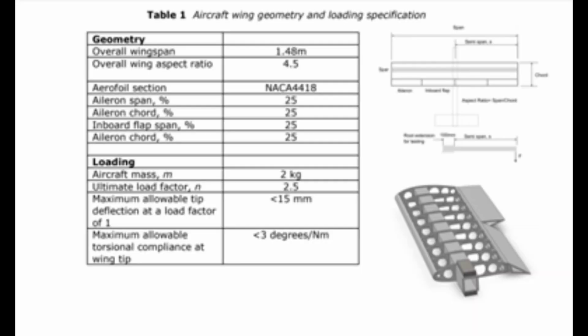The goal of this project was to design and create a wing section out of foam board, following an iterative design process. This task was set with parameters of limiting the mass, preventing failure under a load factor of 2, and withstanding bending and torsion constraints.